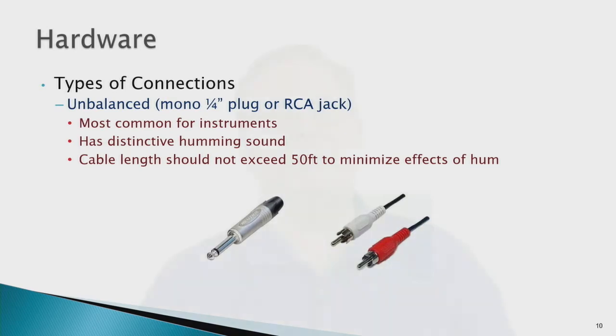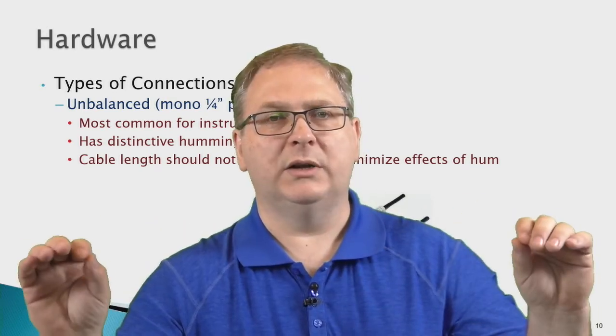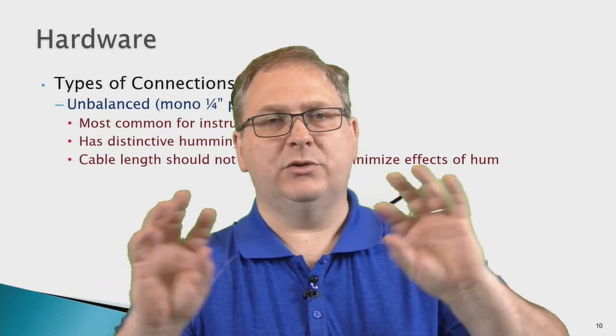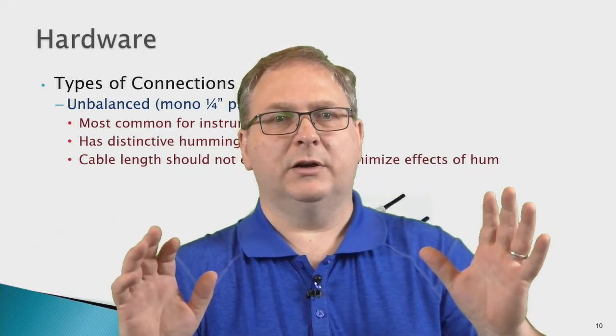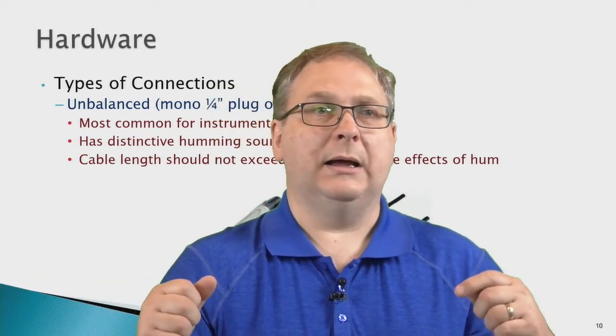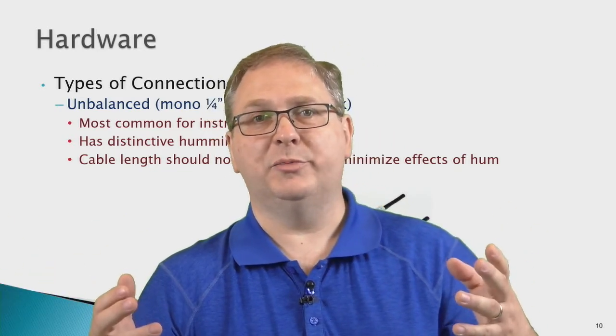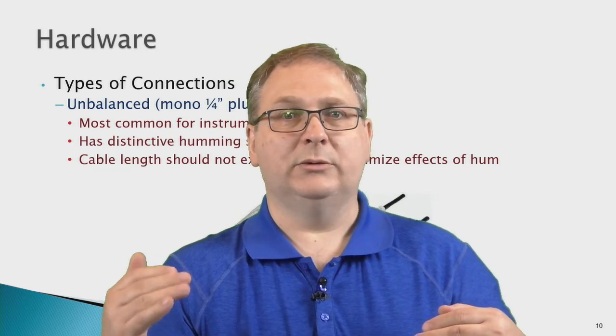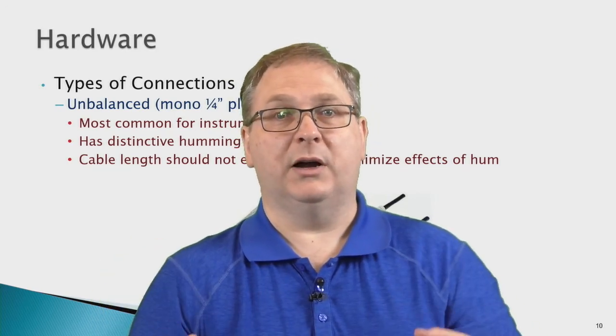And stay away from very long runs, because what happens is that you create a ground loop. And if you want to know more about that, I've already made a video on how to eliminate hum on your PA system, and that talks about ground loops, what they are, and how to get rid of the hum.